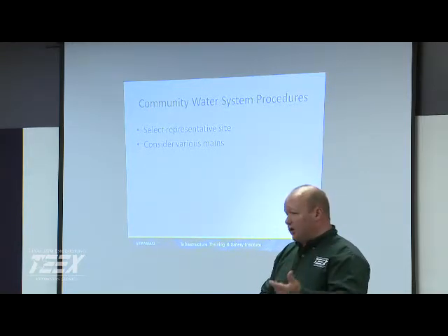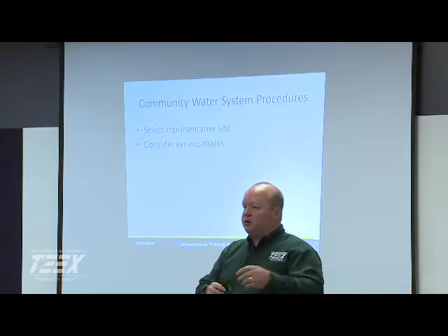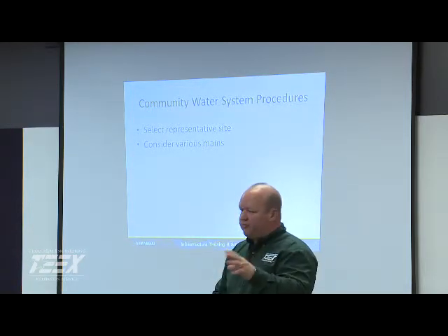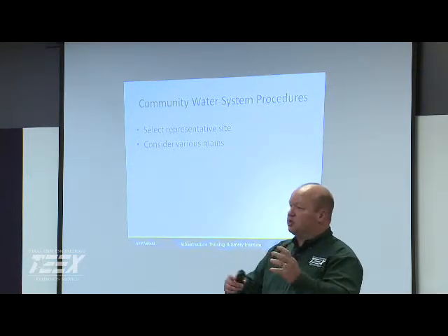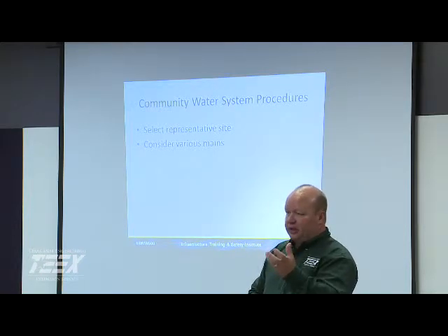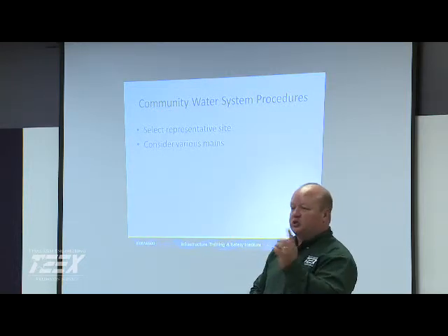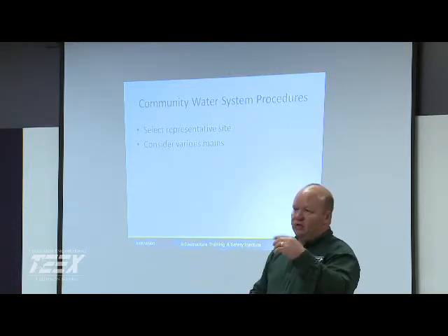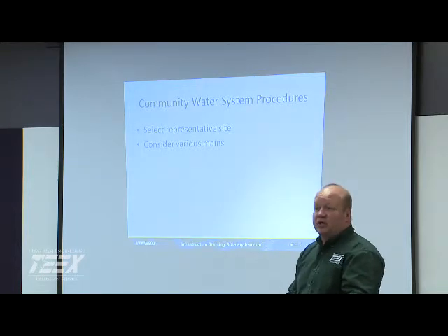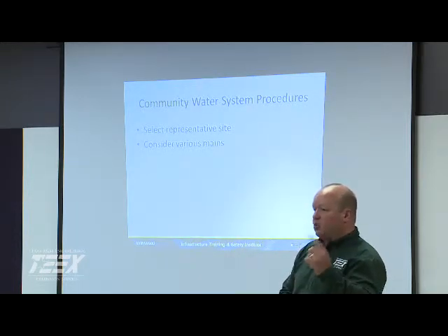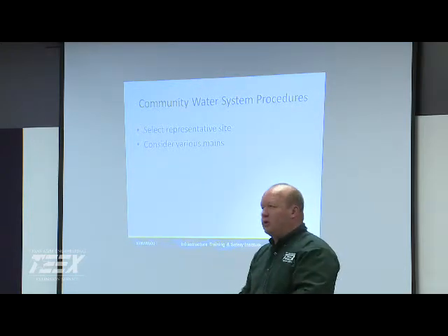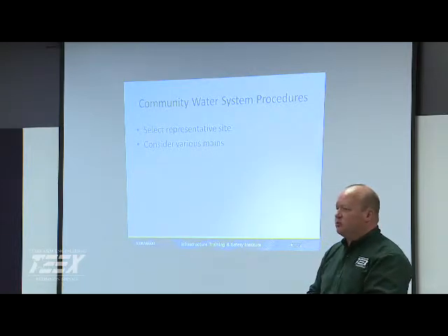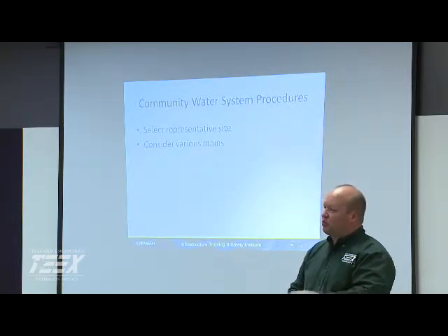But if you get into a regular program, the good thing about the truck-mounted ones is they run off a PLC program, and when it starts to turn, it starts off at real low torque and starts to manipulate it. Then as it starts to feel that resistance hit, it starts to increase slowly but surely until it finds the direction it needs to go. A lot of them you can program in the valve size, so it knows about how many turns it needs to run. It'll slow down as it gets to the stop. They're really neat programs. And you can probably get one, I think, truck mounted maybe under $1,000. Oh, really? I think maybe 3,000.